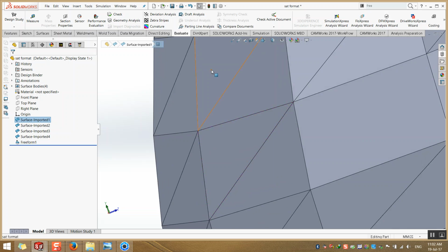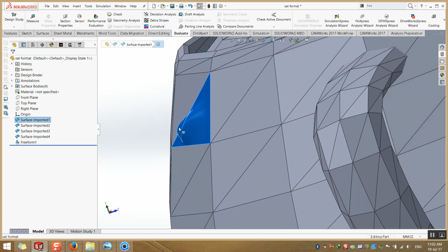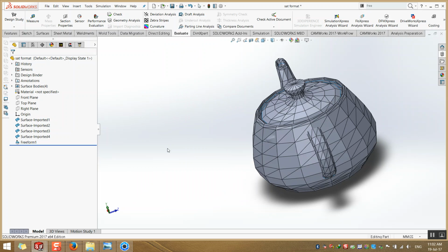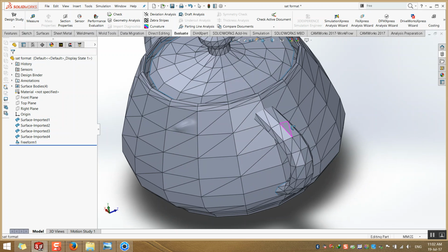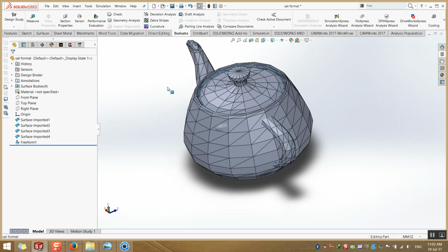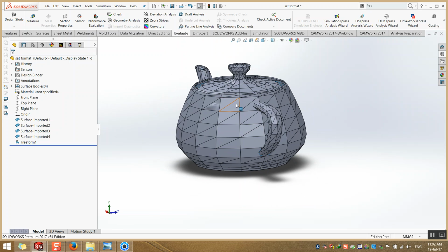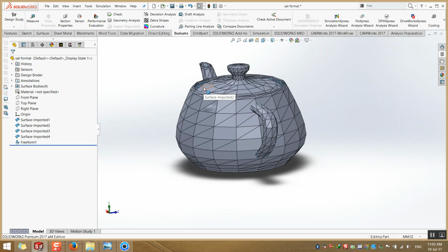In SolidWorks, there's a smooth command like that. Smoothness you can do for the objects that were created by SolidWorks, okay? But this is imported from another software, okay? You should multiply in U and V, okay? Increase the lines in U and V direction before importing it.